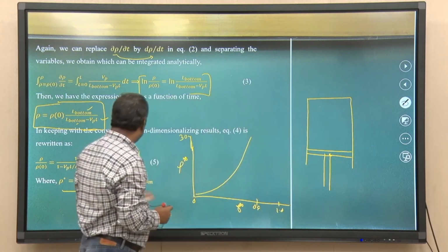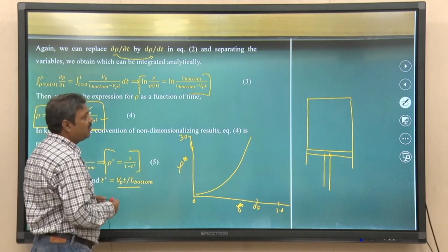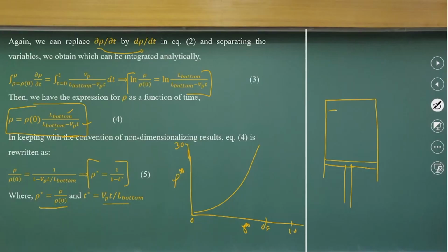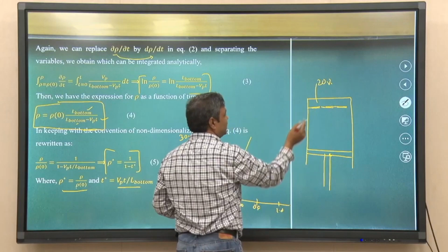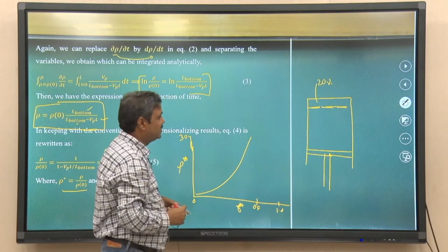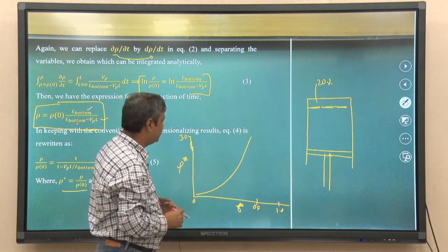In the problem, the density will come out as an infinite value. That is the reason in most internal combustion engines, we have 20% left for clearance volume. That is how far the piston moves up; that is what is feasible. We cannot make the density infinity. As you are compressing it, for a real case we cannot make the density infinite.